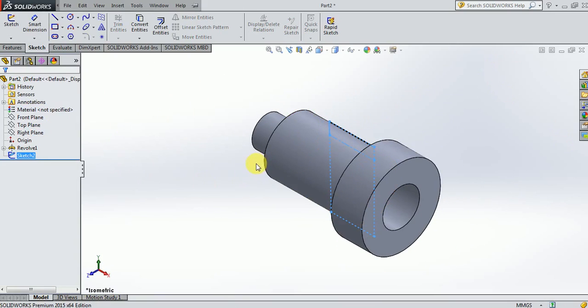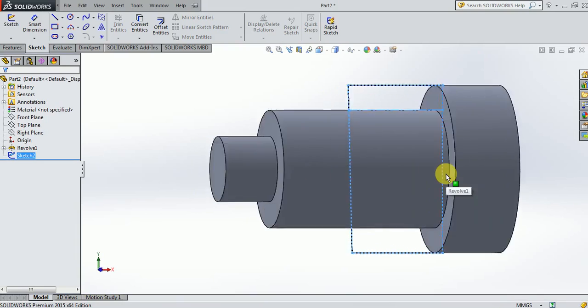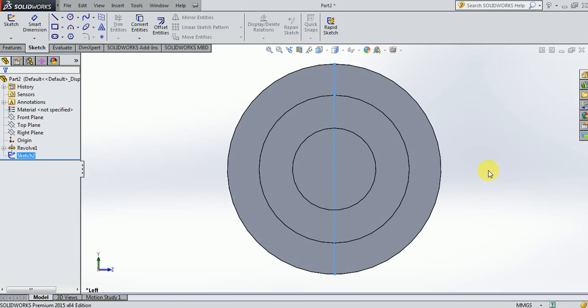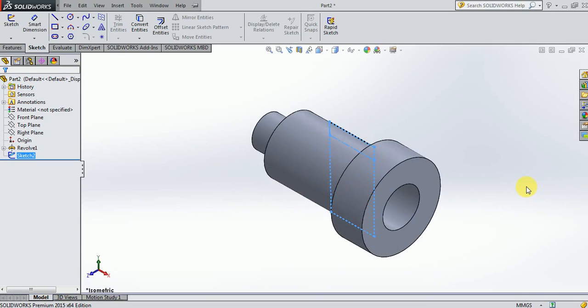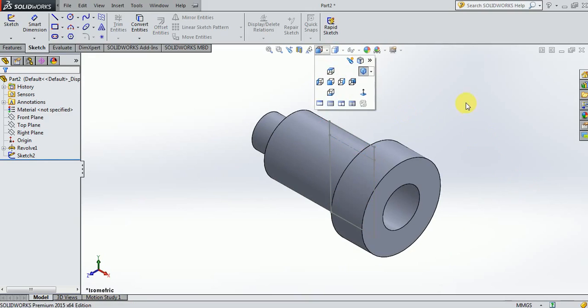Okay, you can press Ctrl 7 to get the isometric view, Ctrl 1 to the front view, Ctrl 3 for getting the side view, and Ctrl 5 for the top view, and Ctrl 7 for the isometric view. Okay, so you can use those shortcuts for changing the views. Otherwise you can change the views here also. Whichever you feel comfortable, you can use that.